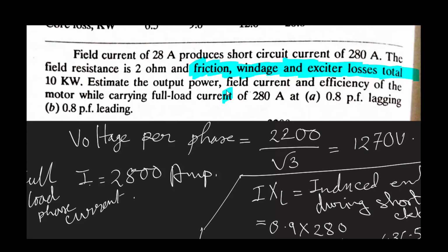Your stator resistance and leakage inductance will play a crucial role and will result in a drop. Therefore, the induced EMF that you had at 1495 no longer remains the same when your speed falls to 1350.